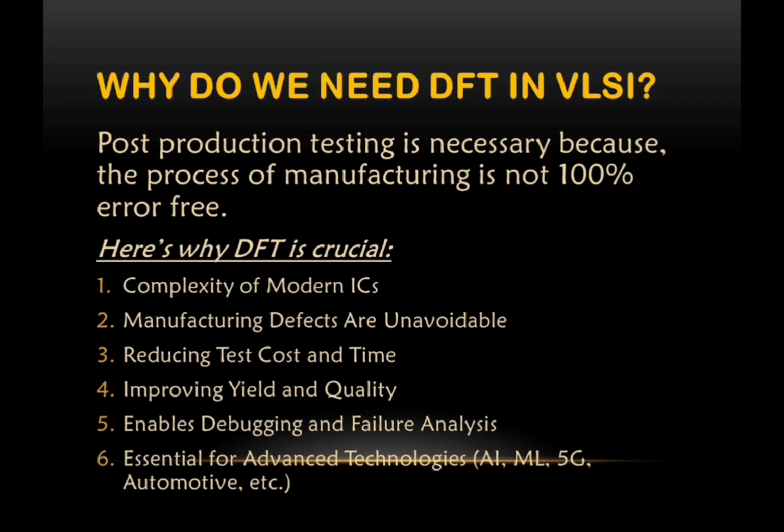The third reason is reducing the test cost and time. DFT ensures these defects are quickly detected and can be isolated. Let us test a chip without using DFT techniques: the result is exhaustive testing, which takes too long and is very expensive. If we perform the same testing on the same chip with the help of DFT, we can use techniques like scan chain and ATPG, and reduce the test time while achieving high fault coverage.